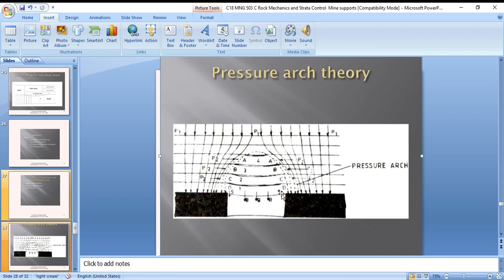The second effect is that the original supports are lost by the excavation and the load is transferred to both sides of the opening. So the pressures P1 and P2 are redistributed to the other areas and also transferred to both sides of the opening, the abutments, where the pressure becomes more than the average pressure. That is very essential to the calculation.